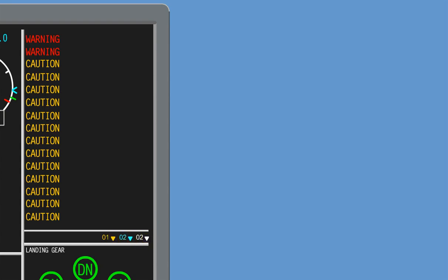The out-of-view message display, digits and arrow, flashes when there are unacknowledged messages out of view. The right out-of-view messages display represents the number of messages out of view below the displayed window, while the left out-of-view message digits represent the number of messages out of view above the displayed window.